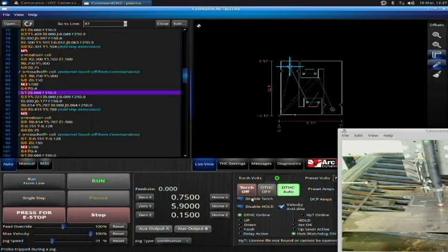And it could be something like air pressure's low. Between the machine stopping, your air pressure might go back up, and you try to cut again, and it continues on. But then later down the line, your air pressure drops, and you get the same error, and it repeatedly has the same problem. And so you don't want to just assume that it stopped for no reason.